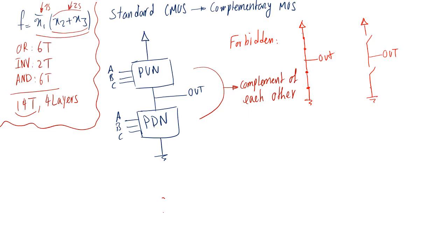Well, we did 2 things at all times when we were designing. There are many ways to implement different logic expressions using MOSFETs, using NMOSs and PMOSs, but this is the standard CMOS way. So there were 2 observations. One, the pull-up network was all PMOS, and the pull-down network was all NMOS. This didn't really help much in terms of being complementary.